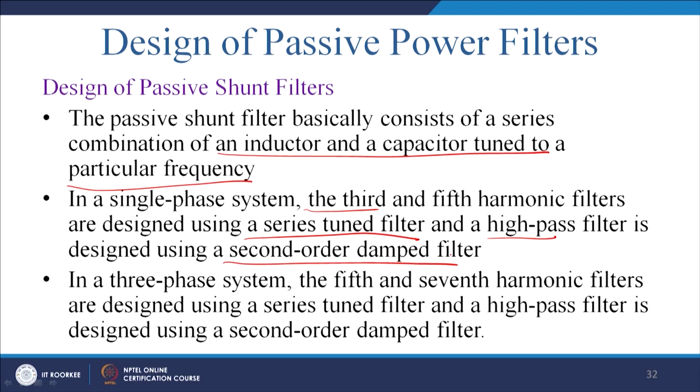We do not want that, otherwise the response will be sluggish. We want L and C, and we put a critical resistance, and thus it is critically damped or very close to critically damped. So, the response is not sluggish, and also you get damping, because a first order never gives you that control.